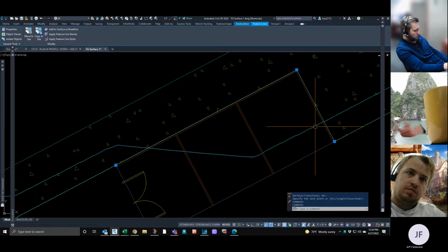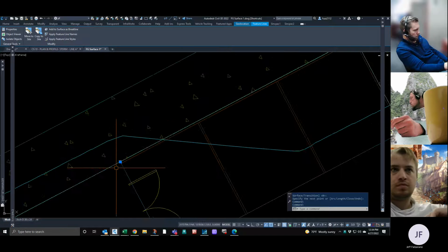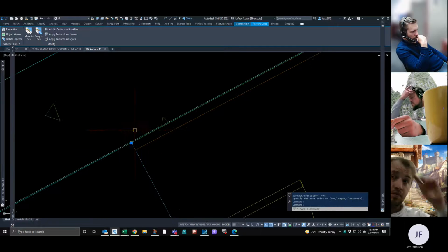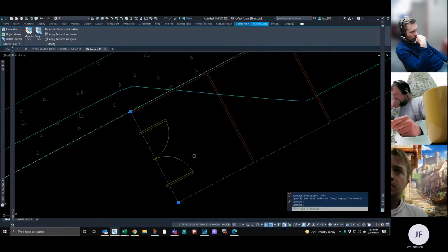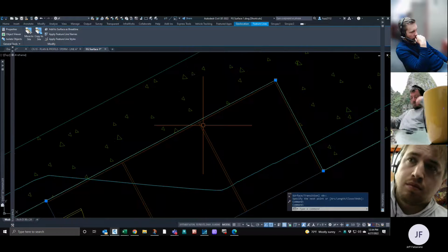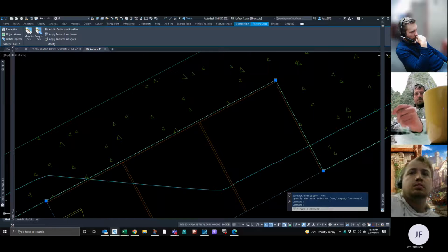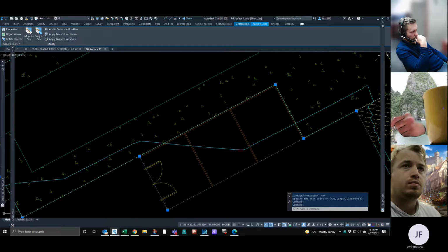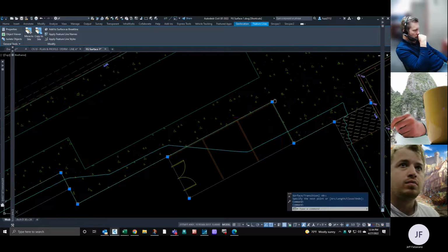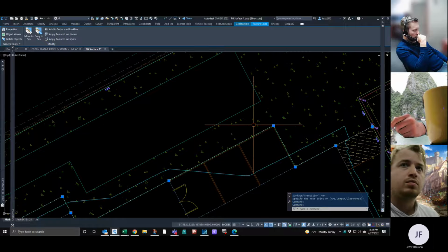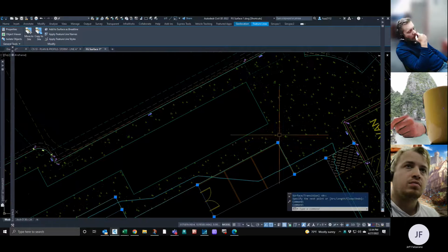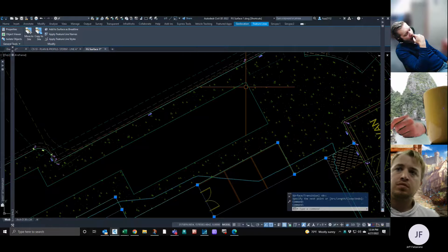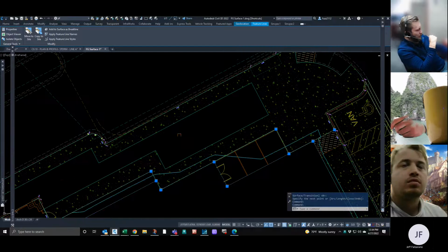So yeah, we're going to just change these elevations to get to this point. So this elevation is at the door elevation. And then we can slope this away in this direction and come down in this direction. Probably be kind of flat going this way, flatter, and then 1.8 in this direction. And then just depending on what your grades look like here, it'll just continue to flow in at 1.8 all the way off the curb.